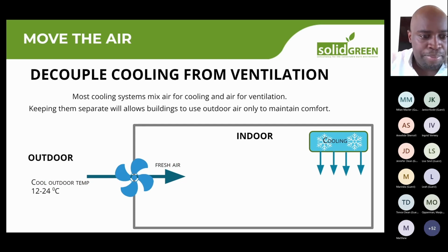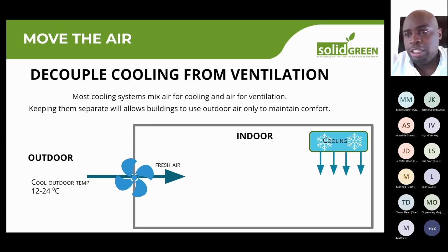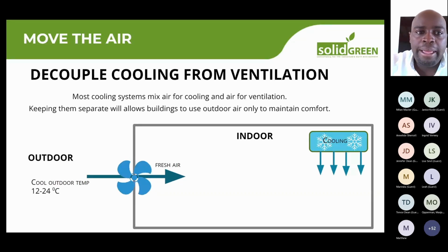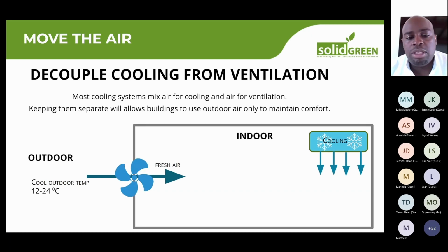And a lot of times when you are on a project, everybody looks to the mechanical engineer to say what systems are going to be energy efficient enough for what we need to do. And the reality now is, because we want things to be off, we also know we need ventilation within the building. So decoupling cooling from ventilation is a key concept, because that means that whenever outdoor air can be used, instead of the cooling system, you run that. So you might find that fresh air being put through the building means that your main AC system can be off from 0 until 10 a.m. And then that's when you need to start cooling.